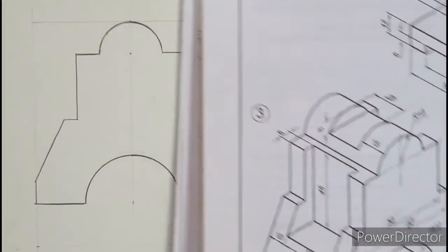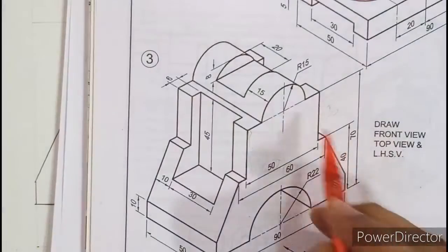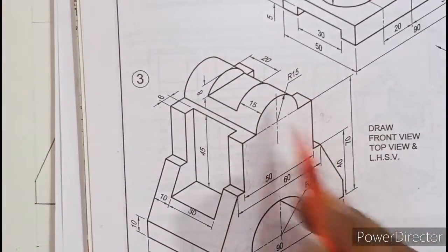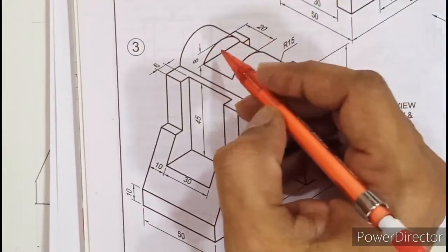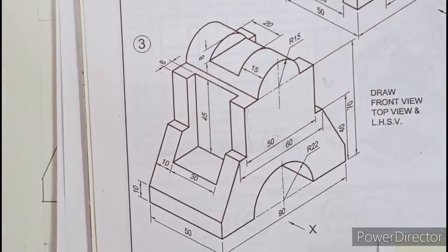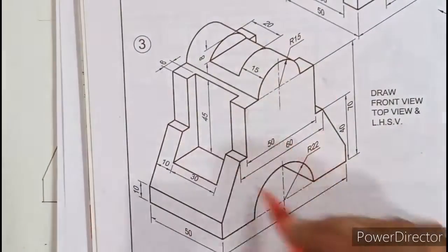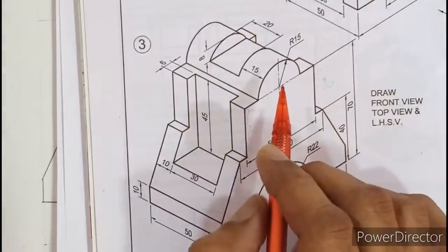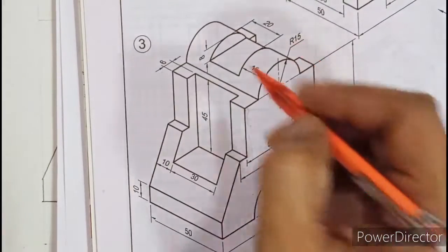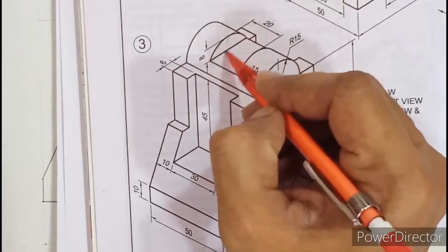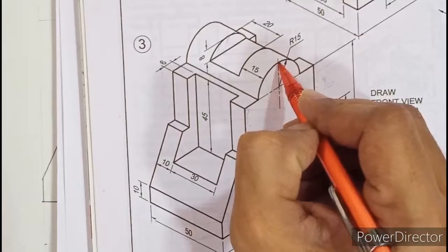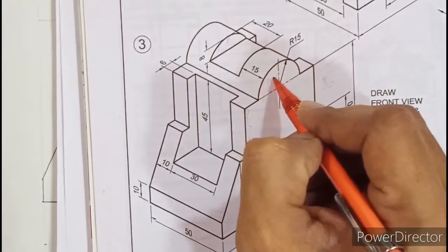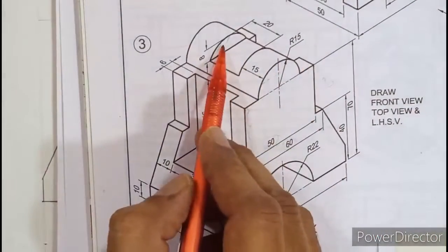So that is what you can see here. The exterior part of the front view is ready. What is left is we need to draw the hidden surfaces within this object. One of the hidden surfaces we have discussed at the beginning, that this arc of the sector cannot be seen from the front, and that is 8 millimeter down. So from this semicircle, if I come down by 8 and draw a hidden line, you will get that arc of the sector.